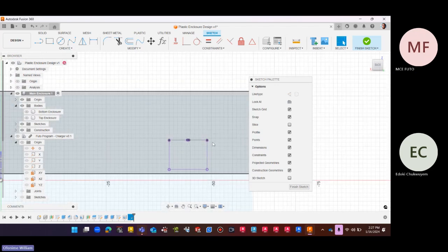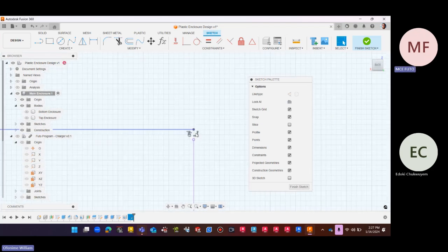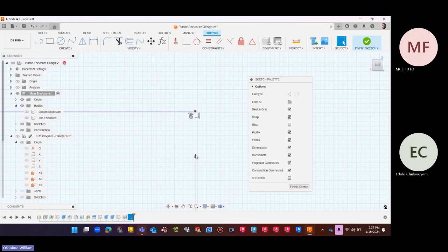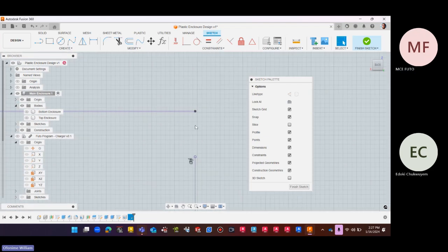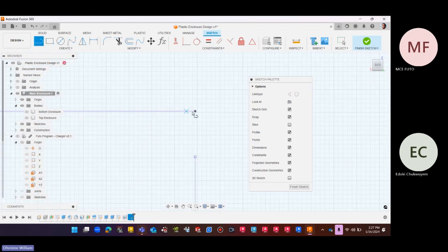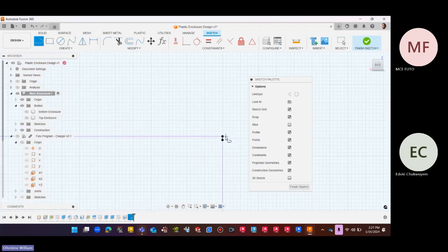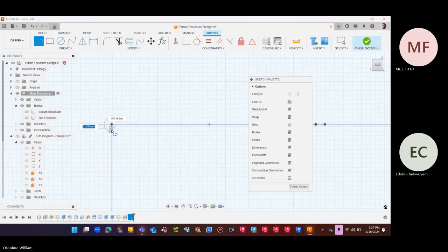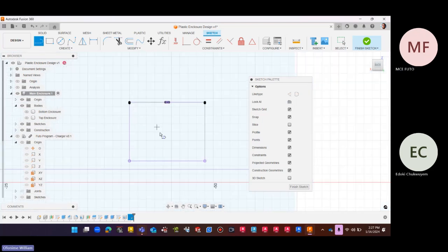You now zoom in. This is where we talk about having broken loops. You can see this. This will not allow us to be able to do our extrusion. So I'll quickly close this up. That's one. Keep on looking if you see another. So immediately you do that, what you notice is that this is now selectable, right?